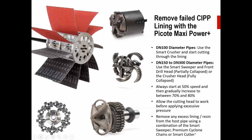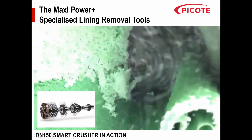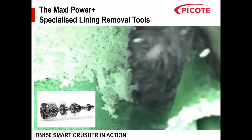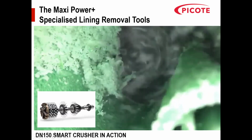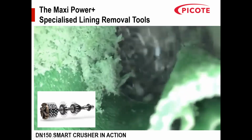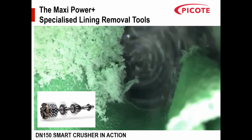If you're so unfortunate as to have what we call a failed liner, then we've got tools that are used for that. Generally, we use a combination of drill heads and the Power Plus. Here's a good example of the machine being used to cut out a failed liner. You can see how it's chipping away at the liner, cutting it into little bits. Depending on the type of liner, we can remove between 3 to 5 meters in a session, an hour.